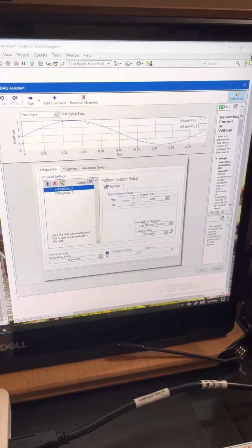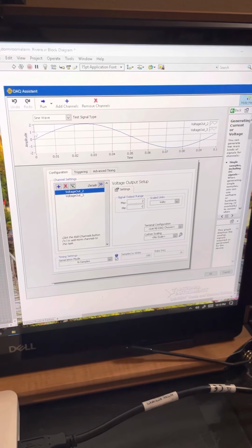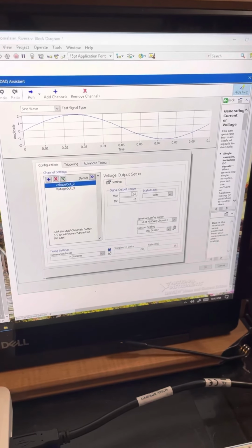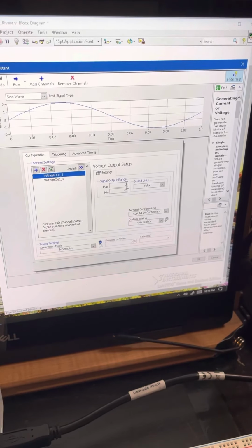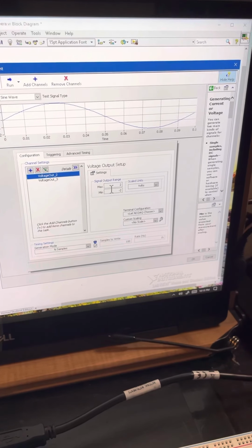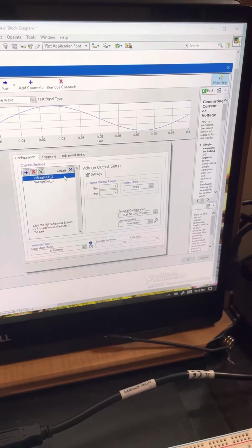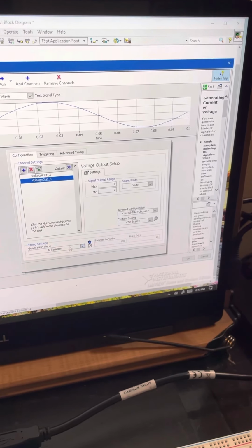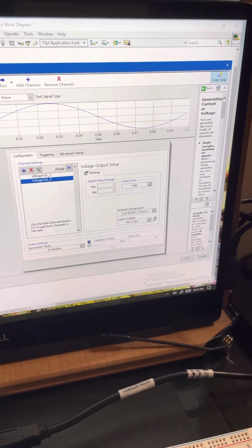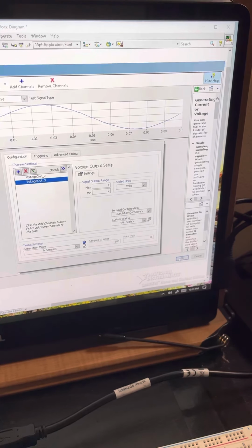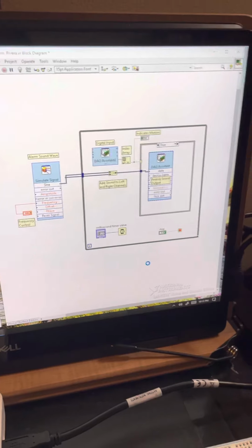That's the same thing as a sine wave, just like you saw previously on the signal output. Your signal output range is going to be 2 maximum and minus 2 minimum for the volts. This is going to happen for both of these channels. The samples are already preset by the myDAQ. So we're going to hit OK there, and it's going to start loading once again.